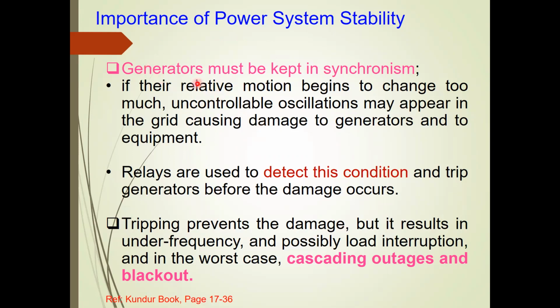Now, when we have several generators, it is very important that these generators operate in synchronism. So we say that these generators have to be kept in synchronous operation. Otherwise the relative motion could change, and that could be too much, and you may observe uncontrollable oscillations that may damage the generators as well as the equipment.